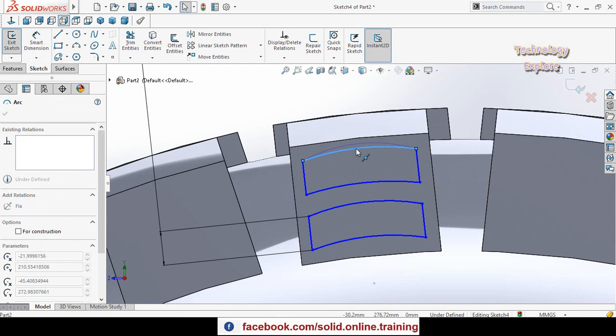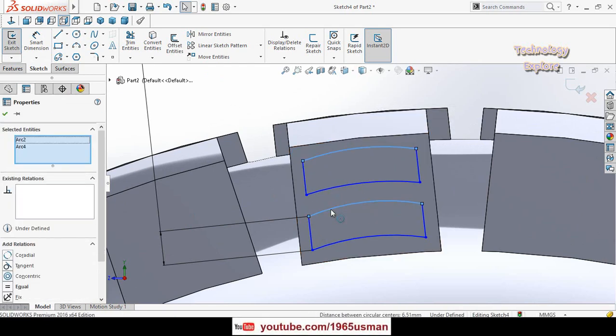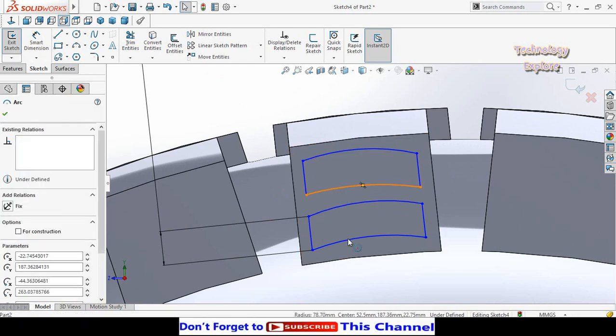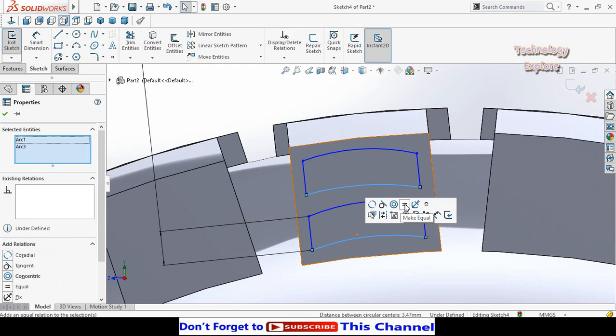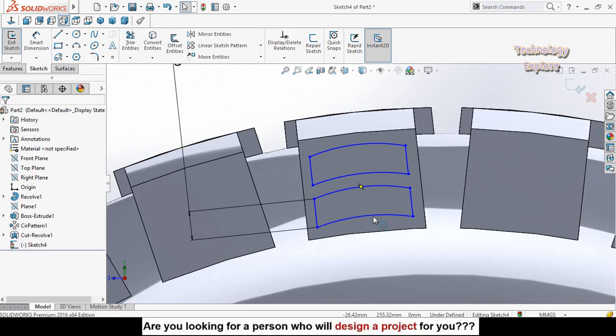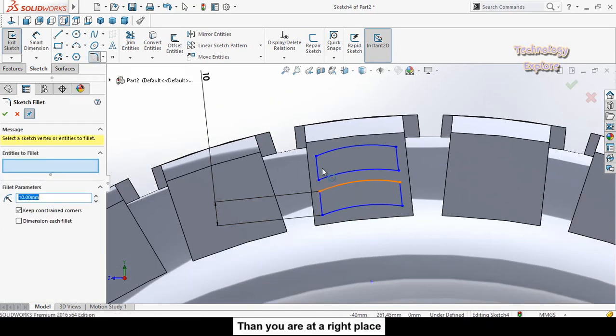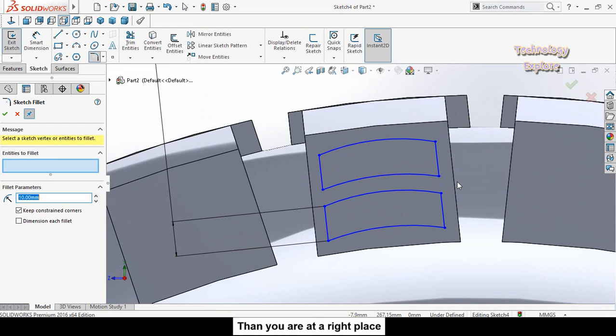Now rearrange the whole sketch. So select this arc and this arc, make their relation equal. Also select these two arcs and make their relation equal. So I think it is enough. Then use sketch fillet from here and fillet all these corners one by one, and fillet radius is 3 mm.